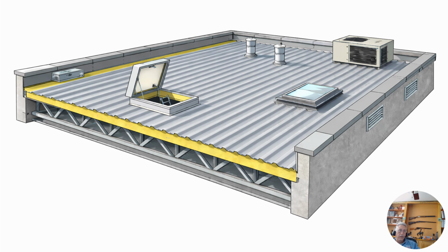This is another graphic I made of a flat roof. So roofs do have windows and doors. Okay, so if you think Schweppes is dumb, I'm here to correct you. So the windows would be skylights. Like I said, this is just a checklist, a mental checklist that I go through. So the doors are the scuttle hole to get through there. And then there's vents. See the vents here on the side? And then there's vent stacks here for like restrooms and break rooms and whatever.